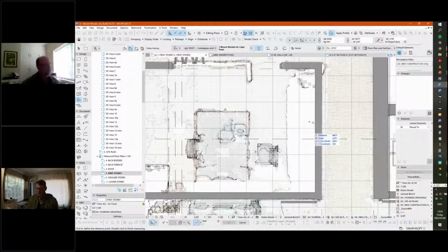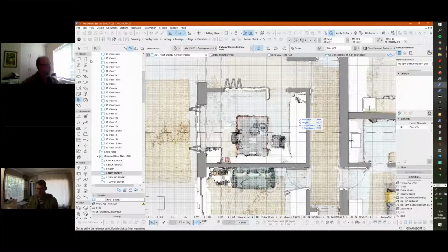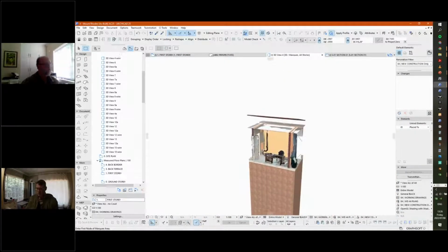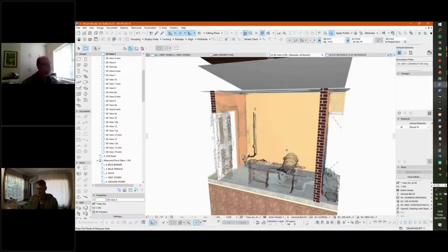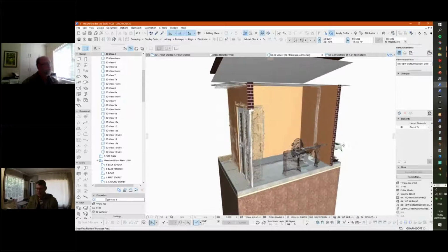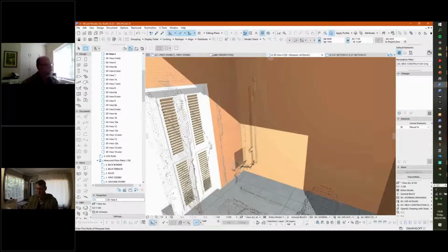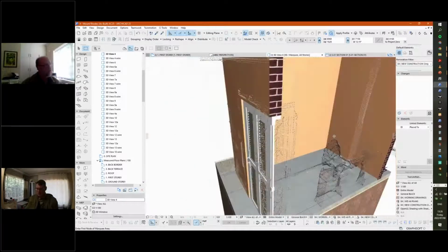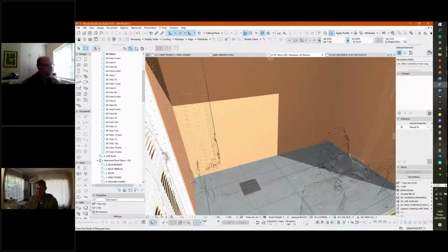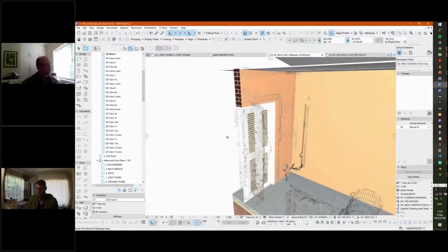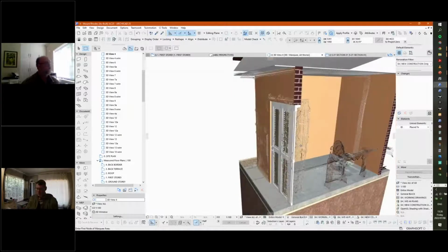In this area, you'll see a blank space on this side of the passage wall, and that would represent a cupboard. So let's go and have a look at this area. I'm just putting a 3D marquee around, going on F5. So this is also another quick way to limit the view that you are getting and in terms of the area that you work with. And you'll see that there is point cloud in this area that shows a cupboard coming up from this distance away from the wall. There you can see the opening leaf, point clouds that show that stacking door open leaf.